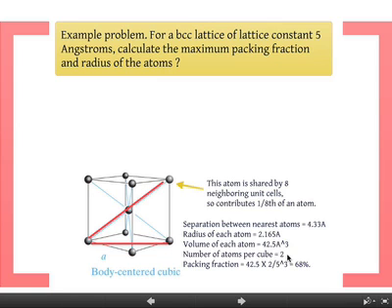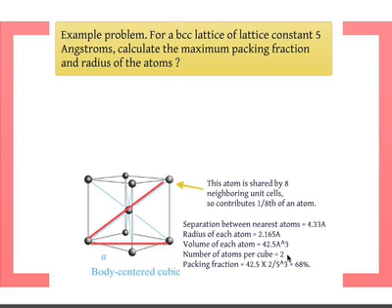Okay, this is kind of important. So we have a cube which gets repeated. How many atoms are actually there? If I count them, 1, 2, 3, 4, 5, 6, 7, 8, 9. I have 9. But of course, only one actually fully belongs to the cube, right? Everything else is shared. So the total number is actually 2, it turns out, because each of the corner atoms are shared between 8 different lattices around it. So you have to only count it 1/8. So remember in that cutoff view, you only saw 1/8. So you have 2.